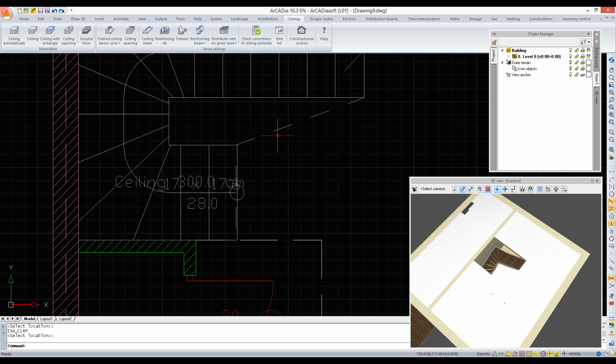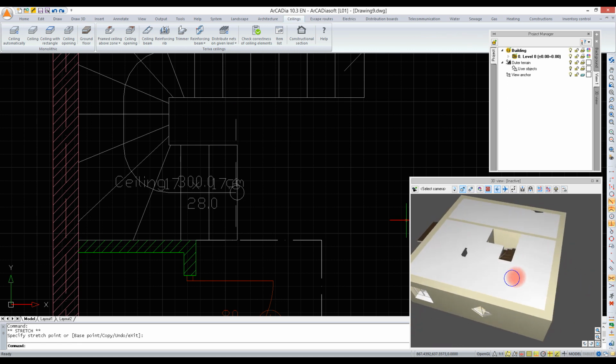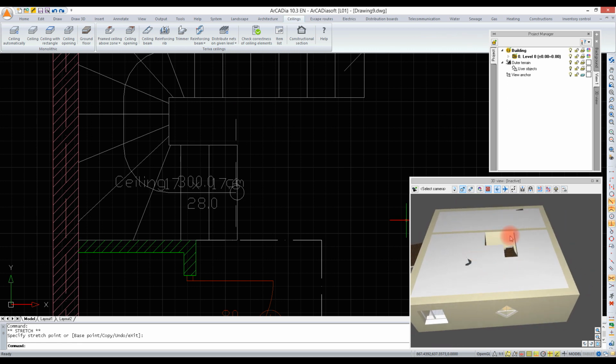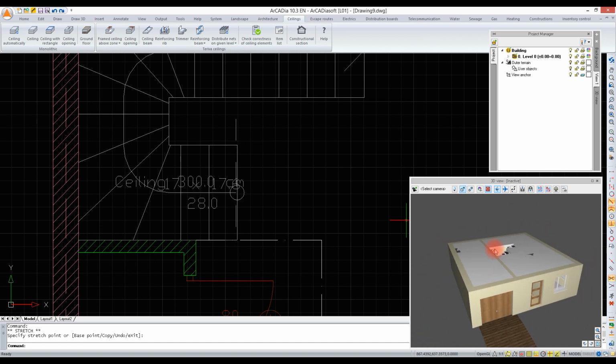After selecting it, in the Edit window and the Delete Point option, we indicate those points that we do not need. We finish with the right mouse button. We select the opening again and we move one of the nodes. And this is how the modified opening looks.